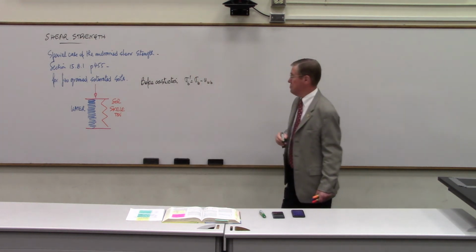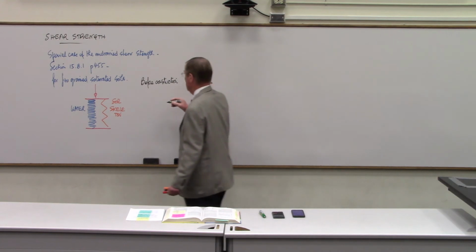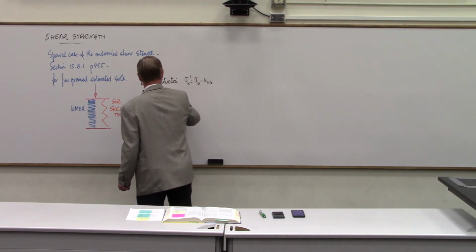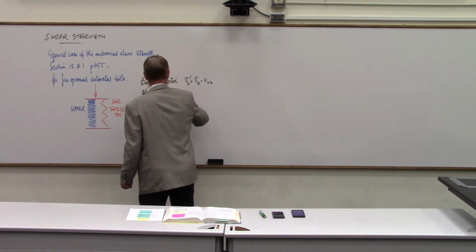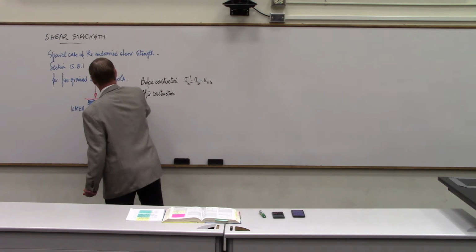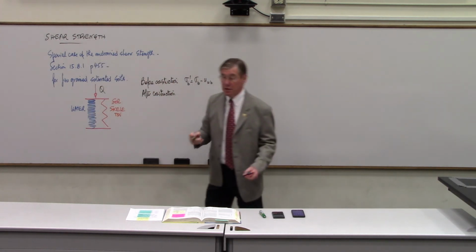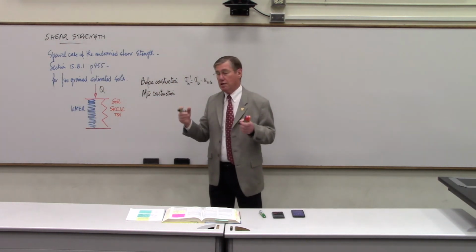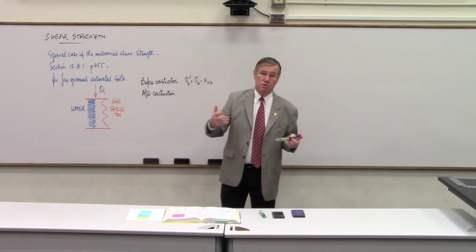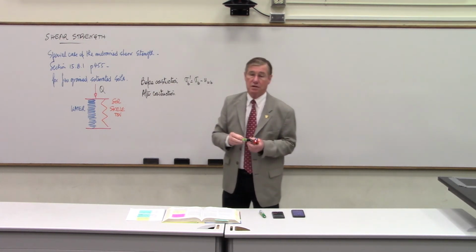Okay? Before construction. After construction, you have applied this big load Q right there. And it's relatively fast. Not that construction is fast. It may take a year, but it may take 20 years for the water to drain out of the fine-grained soil.